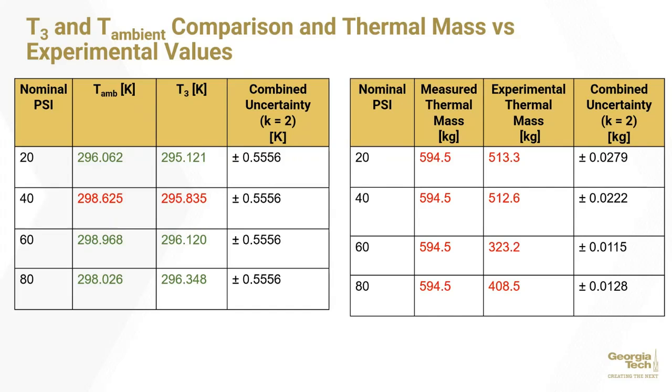The discrepancies here can be from residual heating from previous experiments, some heating from the environment, from the fact that the pipes are not perfectly insulated, and also the fact that the heat exchanger and the accumulator are thermal loads that are not accounted for.